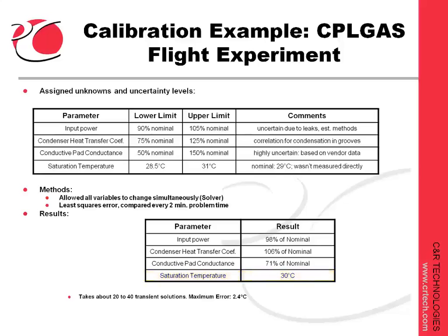itself. The conduction of the pad underneath the thick plate was overestimated, but that's not surprising since only vendor data was available before the test, and they don't sell a lot of pads if they underestimate their performance. Finally, the heat transfer coefficient for condensation wasn't too far off.